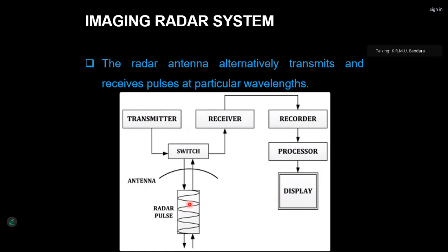Then after this line, out of focus, the satellite goes to the next line. Then the next pulse is sent, receiving is off. Then the next pulse's returning signal starts going back to the antenna, the switch is on for receiving and off for transmission. Like this, line by line is scanned and recorded here. Okay, how many pulses are sent? 1500 pulses per second are sent to the ground.